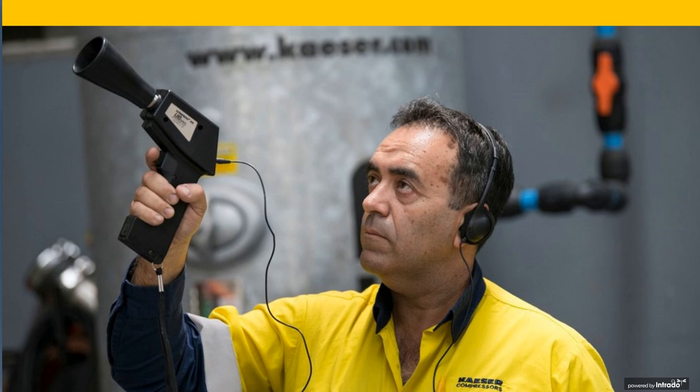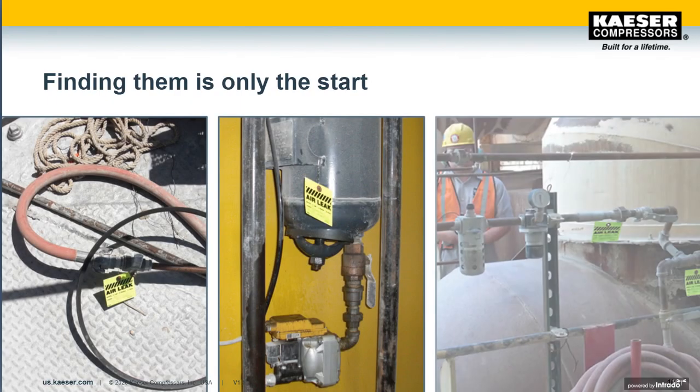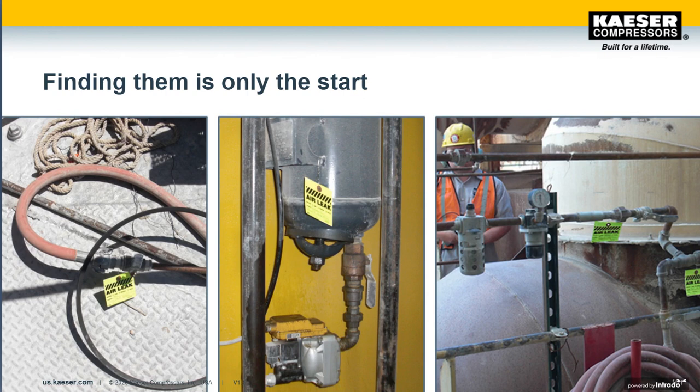Consider the 80-20 rule. Keep in mind, too, that some pipe materials will corrode over time, and that these materials leak more than non-corrosive materials such as copper or aluminum. If you've got pipe in your facility that can corrode over time, consider making changes to avoid future problems. Remember that the more your system leaks, the more compressed air you'll need now and forever. You can't stress enough, when you find those leaks, fix them.